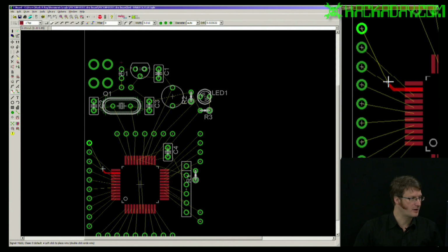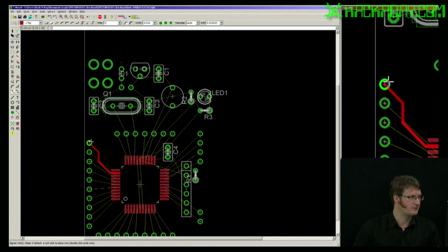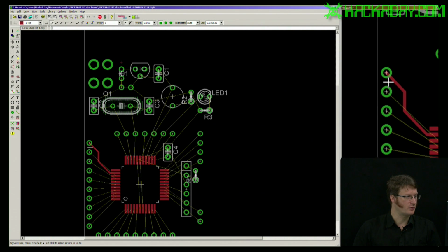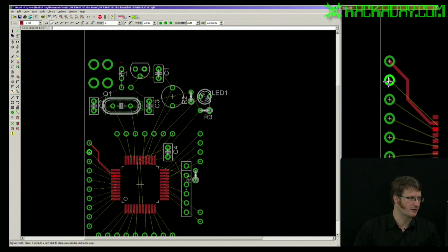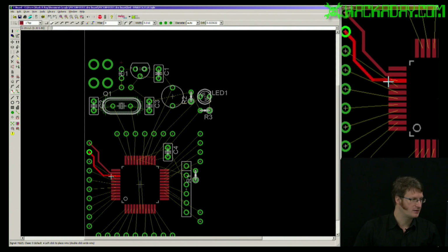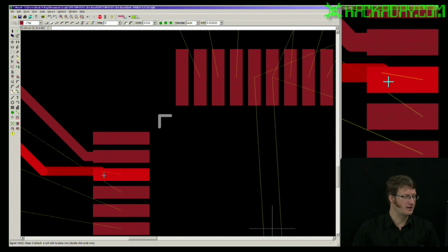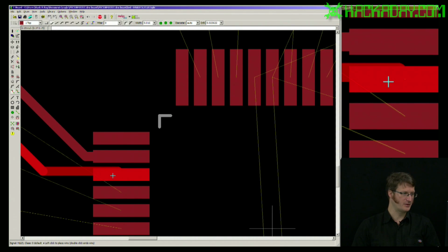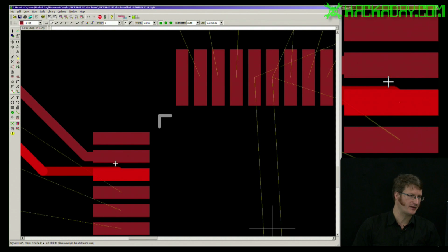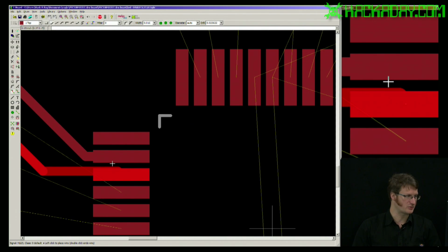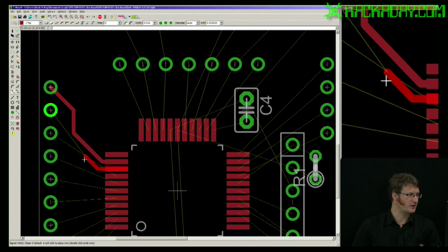If I go here and I go to route that, it lines up just perfectly with this pad. And I'll just finish taking that, and the computer will beep when you have completed a route. Now let's try to do this route, and I'll show you what happens if I start here. So far so good, but as you can see, I haven't lined up quite right with the pad. And depending on how different the spacing of the part is from the grid, you may have trouble. So like maybe this right here, this spacing would violate the minimum spacing that my board manufacturer would require. Most likely it wouldn't, but we'll just undo what we did and we'll route from here.